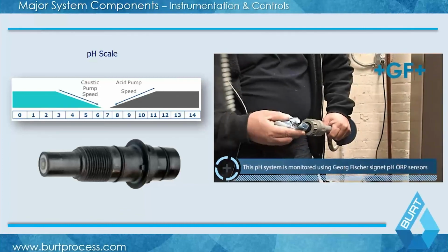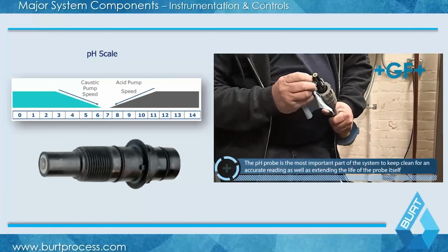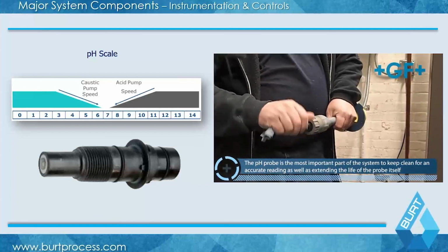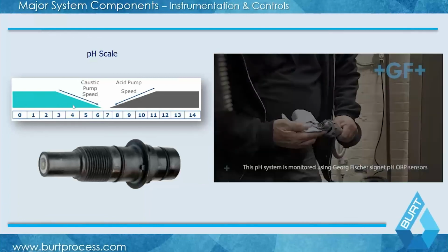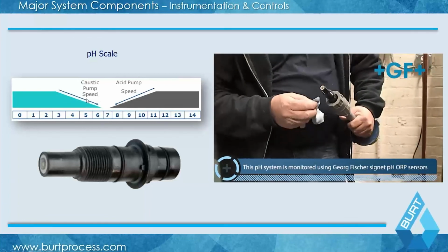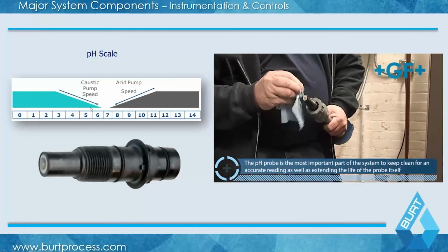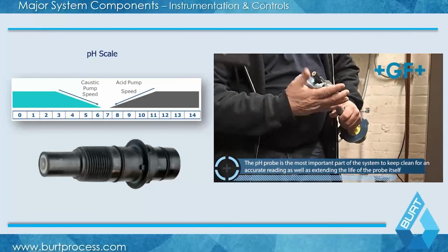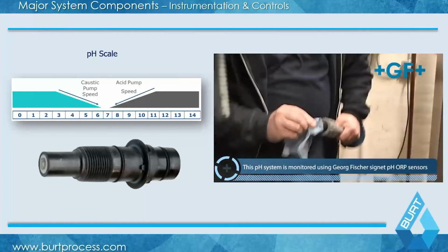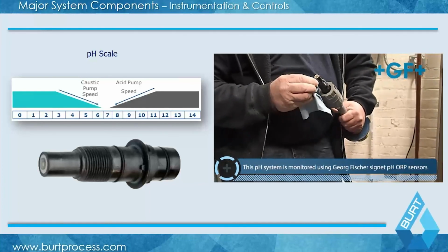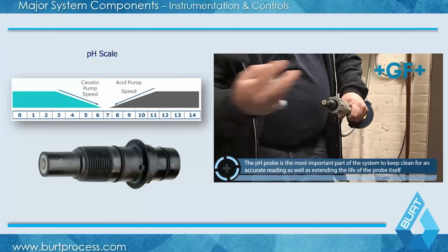You're much closer to the strength of your reagents, and you're going to run your pump at a higher dosing rate, whether you have a single stage or a two-stage style system. And as you get closer to neutral, you basically scale down proportional to the pH curve until, as you go from 4 to 5 to 6 to then 7, you're proportionally turning down your metering pump by a factor of 10, 100, 1,000, etc., to meet that goal. And this is based on the real-time feedback that comes from the pH instrumentation located in your pH system.